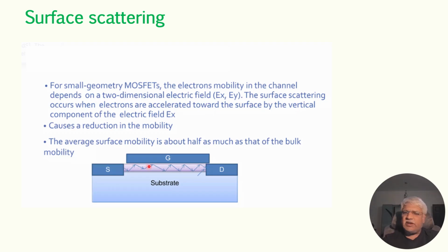It will have so many ripples and hillocks, and hence when the electron touches that part, it gets repulsed. In the sense like it will get reflected, and this scattering is happening at the surface. So the mobility of the electron is not a smooth function, but it is affected due to the two fields, hence, especially more predominant in the short channel, the mobility gets reduced.